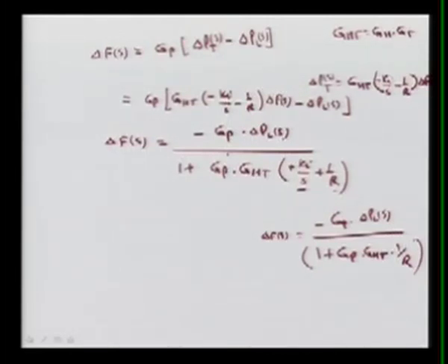So to this, for the change in Fss, again we can use the final value theorem, and that is nothing but the limit S tends to 0 of S into change in Fs, means first we have to put S and then put the value S equal to 0, and then you can get it. Again here the change in PL is some constant, X upon S, because we are talking about the step response. So we can put this value and then we can go for this.